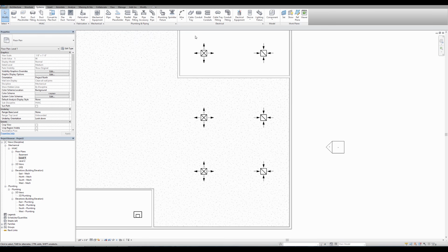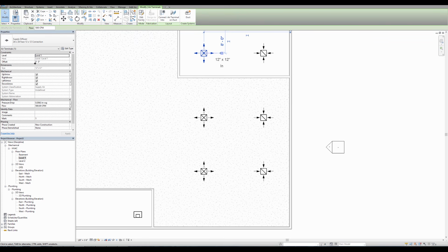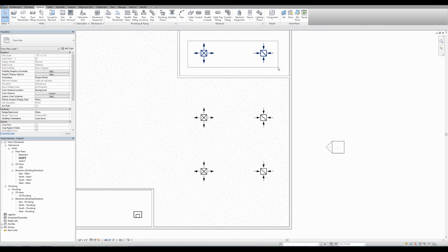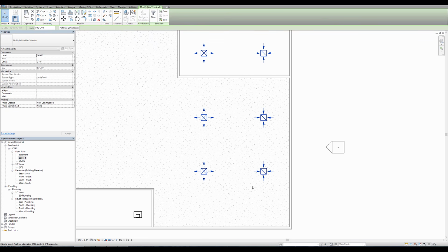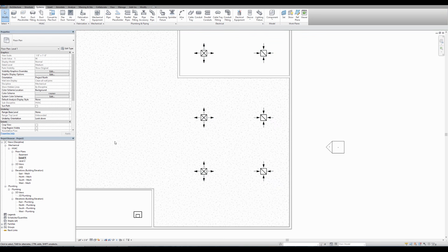We also need to offset the ducts because we actually didn't put an offset on them and they're currently set at 0 feet. So you can just select them all and then offset them all together. Let's say our ceiling is 9 feet or so. I'm going to adjust this to 9 feet, and you can adjust yours based off the requirements of your ceiling. Okay, so we have everything in place.